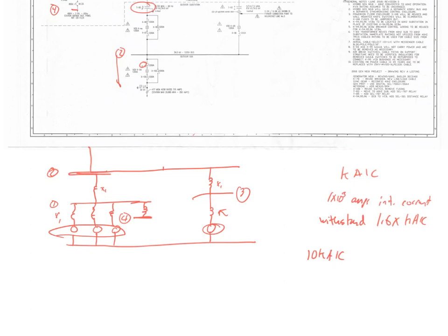But does 10,000 amps seem like a lot of current? Actually, it's nickels and dimes. I worked on a system in Washington, D.C. that had 210,000 amps of fault current. So when you have current levels that are over 200,000, you use something called current limiting fuses, and some of the distribution circuits actually use current limiting fuses.